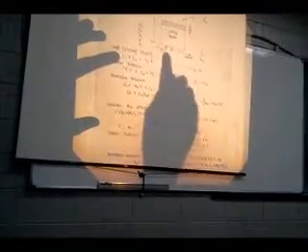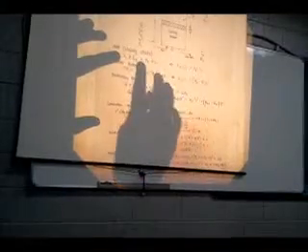So in setting up the overall mass balance, assuming steady state, we have V1 plus L2, which is the entering air and entering water, equal to V2 plus L1, which is the exiting air and the exiting water. Rearranging, we have L2 minus L1 is equal to V2 minus V1.